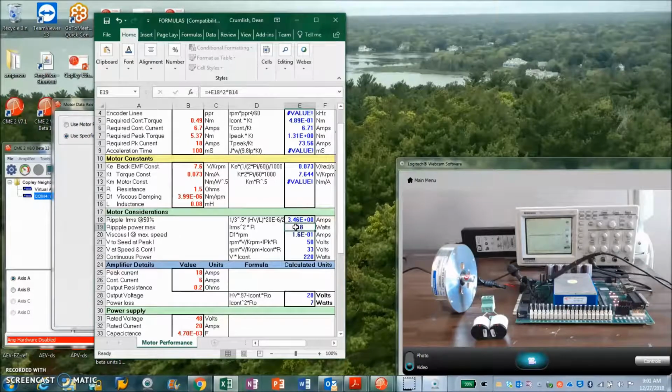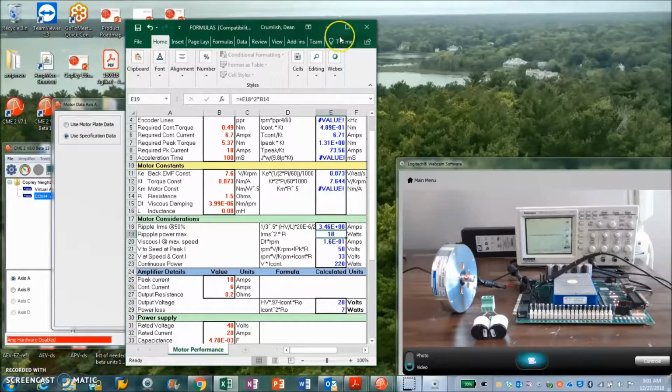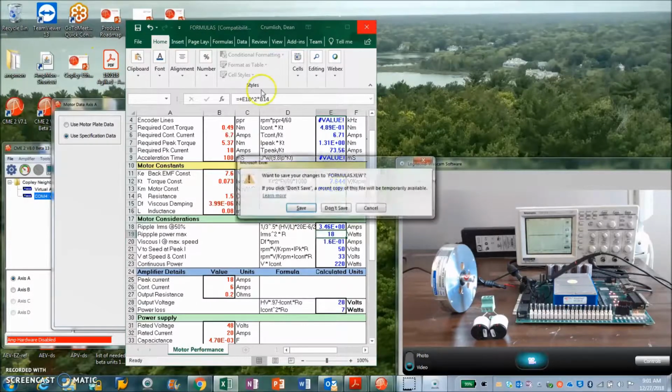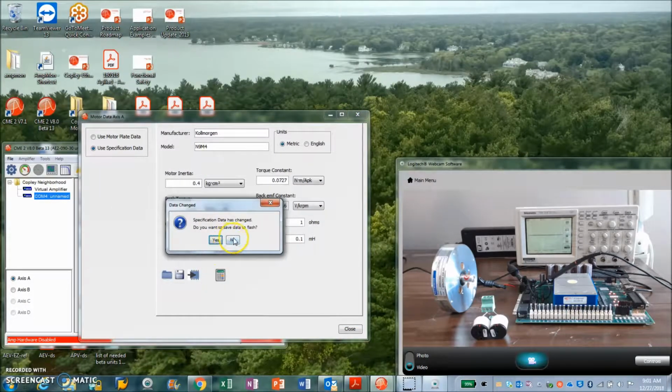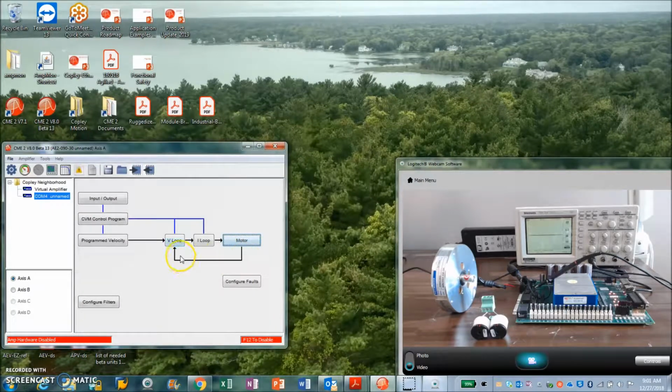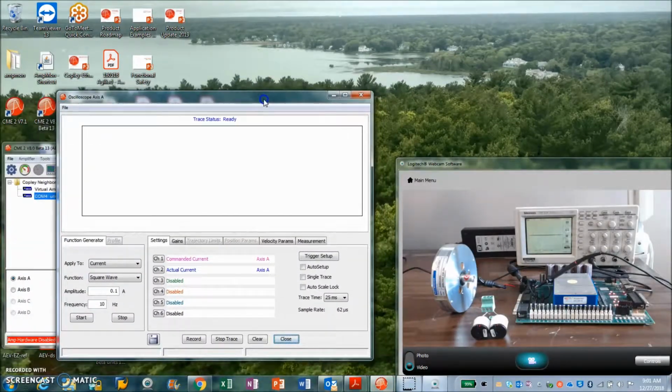And there's a case when we're trying to control the current with a PWM amplifier. If there's ringing at the time of the current measurement, then we could get some funny readings. So I think that's what happened here with this motor. But anyways, we calculated the initial tuning values and looked at the current here. So what I'm going to do is take a look at the runaway condition that occurs without adding some inductors.